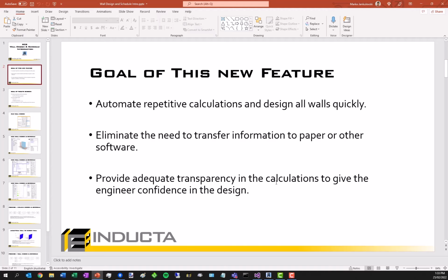This new tool is comprehensive in relation to wall design, looking at all relevant clauses from Section 2, Section 8, shear as beam, Section 10, designing as a column for strength, Section 11, wall, Section 14, the new earthquake requirements, and we fully incorporate the latest amendment, which is amendment number 2.